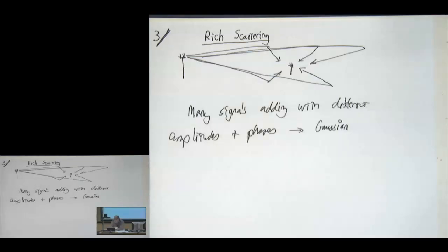And the places where it wouldn't make sense would be places where you don't have a lot of scattering. So satellite to satellite communication, free space, aside from the junk floating around, there's not a lot of reflections. And so Rayleigh fading wouldn't make a lot of sense. Receiving in this room, we do have a lot of scatterers, so it might be okay. So that's just giving you some intuition here.